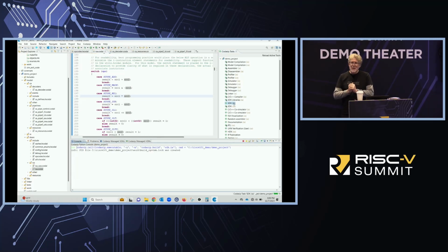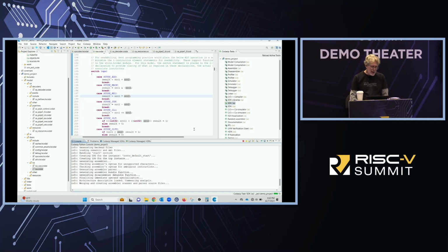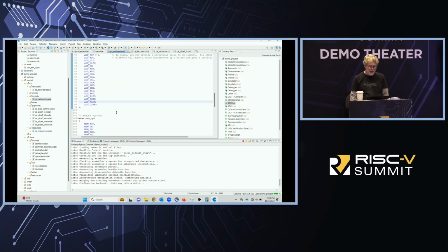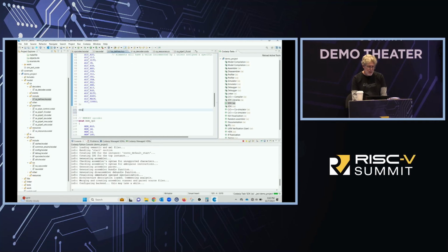But now, once again, I could somewhat add a multiply in the ALU, but it should be its own compute element. So I'm going to actually show you how to add the compute element. Now, I got to go back because I need a few additional resources. But first of all, let's go in my define, and I'm going to actually create a new enum. Like you can see up here, I have an enum for my ALU microops. I'm going to do an enum for my multiply.